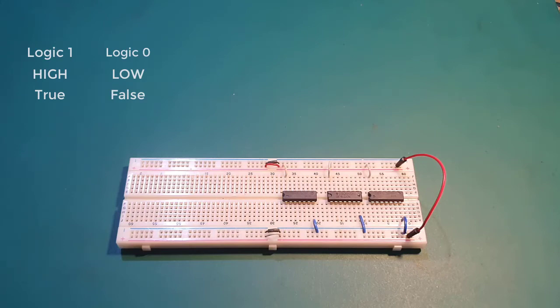IC can recognize. For example, in a TTL IC, voltage levels from 2 volts up to 5 volts are considered as logic 1, while 0.8 volts down to 0 volts is considered as logic 0. The voltage region in between these two voltage levels, either as an input or as an output, is called the indeterminate region. And operating within this region may cause the logic gate to produce an inaccurate result.